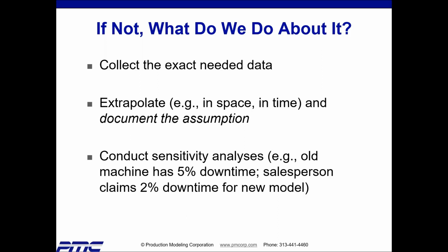Now, the model with the hypothetical new machine in it may produce just about no more than the old model did. Well, that would tell you the model is insensitive to the downtime of that machine. And insensitive, that's where this term sensitivity analysis comes from. So we don't need the new machine. We probably need to correct bottlenecks and difficulties elsewhere in our production process. So it was a nice lunch with the salesperson and we say thanks, but not right now.